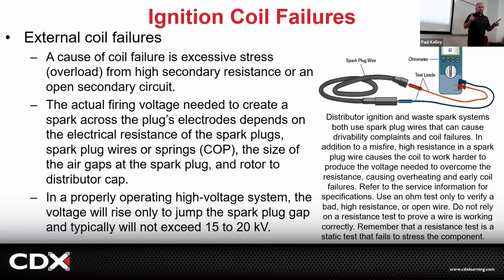But I had a class at one point, they went to diagnose a vehicle that belonged to a staff member of the school, and they pulled the coils out to do their testing, and they cranked and cranked, and they did measurements, and they cranked and cranked and cranked, and they ran it. They actually killed several coils in their testing. So when a coil's completely disconnected from the spark plug, it's going to try to arc wherever it can. That hurts the coil.